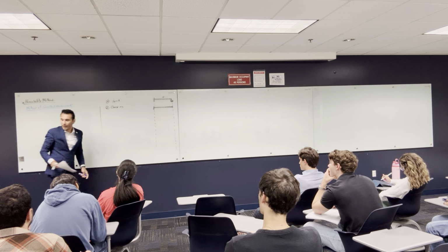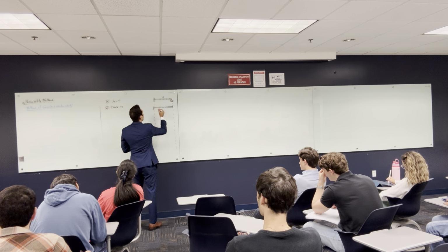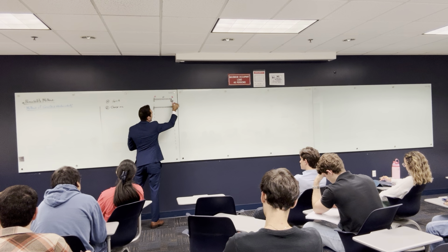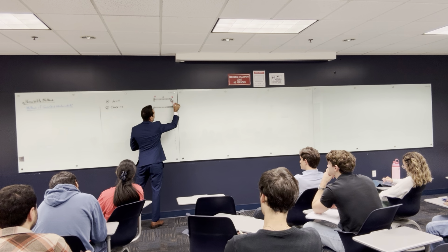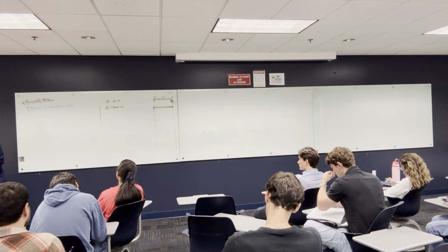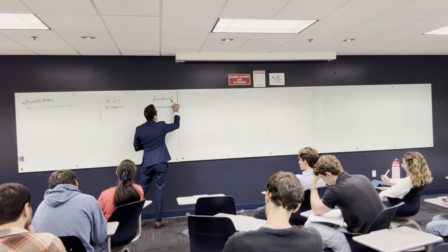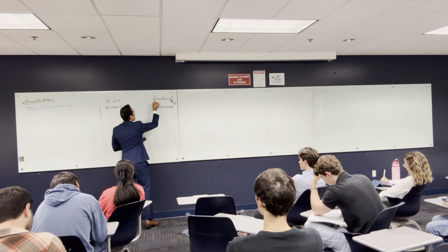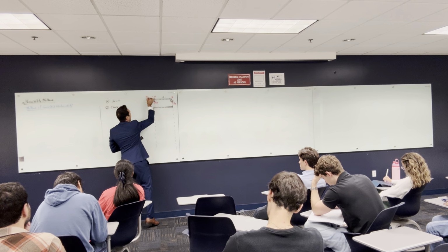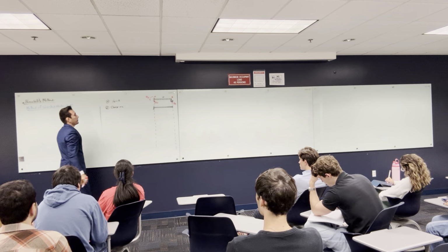But let's think about it that way. The reactions that I have here in this problem, let's say this is point A and this is point B. What reactions do I have? I have here Y, B. Well, let's be consistent with what I have. I put here RB. So let's call them RA and RB. Here I have RB, and here I have RA, and I have a moment here, MA. I can say I have X, but definitely X is equal to 0 because I don't have any X forces. You can say XA or something.